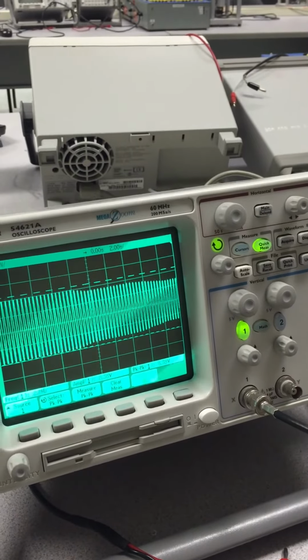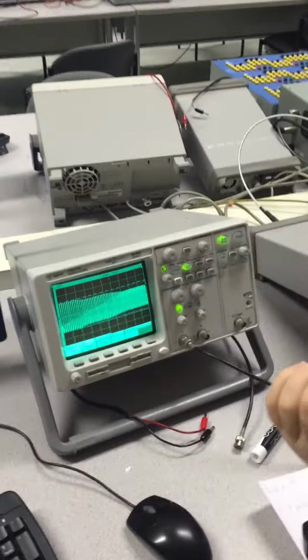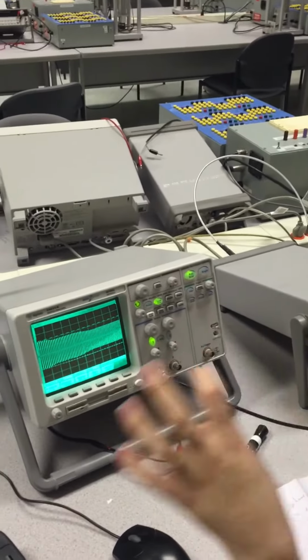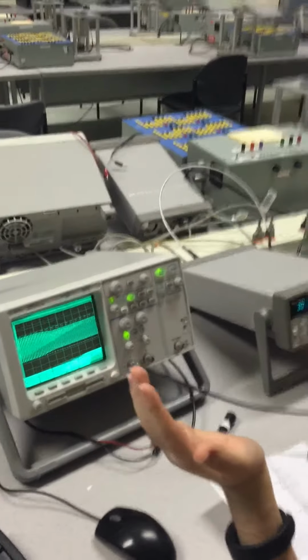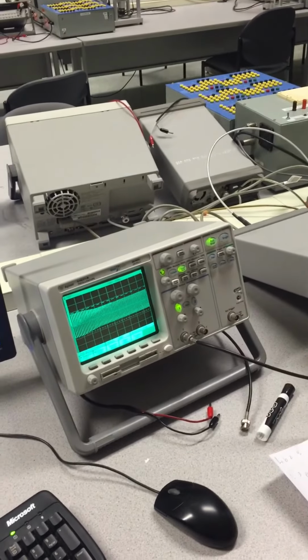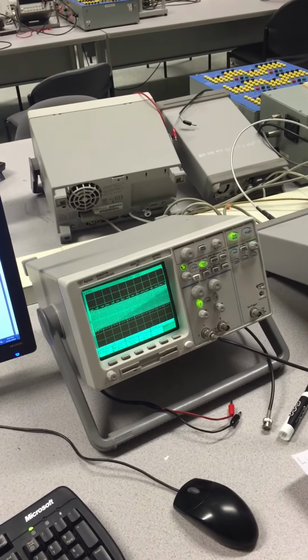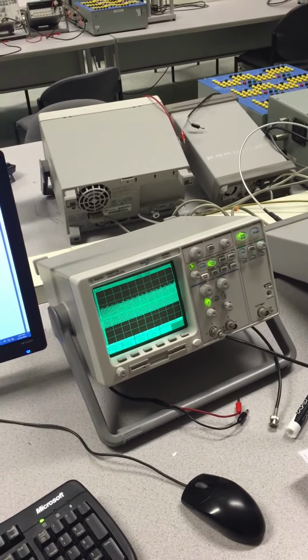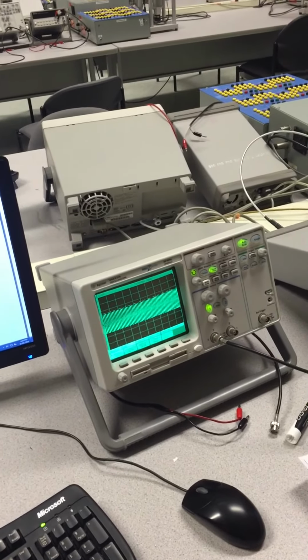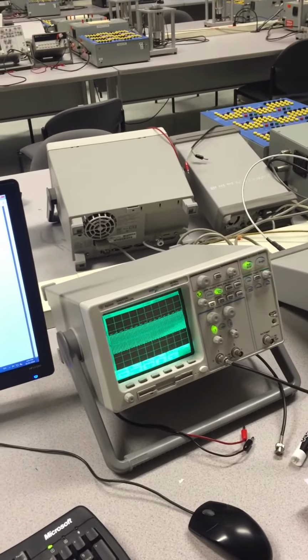So what will happen is, we start with a small amplitude, we end with a small amplitude, and the maximum amplitude is somewhere in between. We started with 100 millihertz, we ended with 3 hertz. The maximum amplitude should be something in between. When you get the maximum amplitude and the maximum frequency, you can find the motor constants A and tau m, and by this the hardware part of this section of this lab is done.